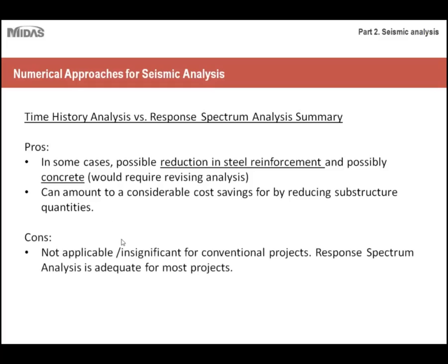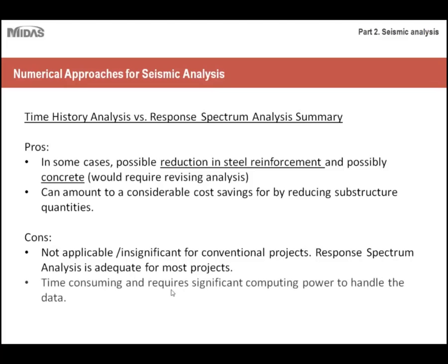It's not applicable, and it's insignificant for conventional type projects. So for example, if you were working on maybe just a regular building in the Midwest, time history analysis wouldn't be realistic to run, and would be too much of a time investment, and you'd be able to achieve results that are completely acceptable with response spectrum analysis. And then it's time consuming and requires a significant amount of computing power to handle all of the data. So that's where numerical modeling programs come into account. So even though you can save a lot of time with numerical modeling programs, time history analysis in and of itself is still a very lengthy process.